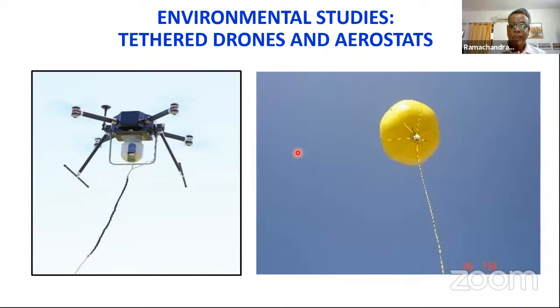And therefore, if you fly an X-copter or a quadcopter and connect it through a cable, a tether, which can get connected to the battery on the ground, it can be at about half a kilometer, 1 kilometer, 2 kilometers in height, but it's connected to the ground and it is mobile. It can be mounted on a mobile vehicle, but this tethered vehicle can run continuously for maybe a day, not just 20 minutes. It can maybe run for two hours, maybe 1 day, maybe 3-4 days.